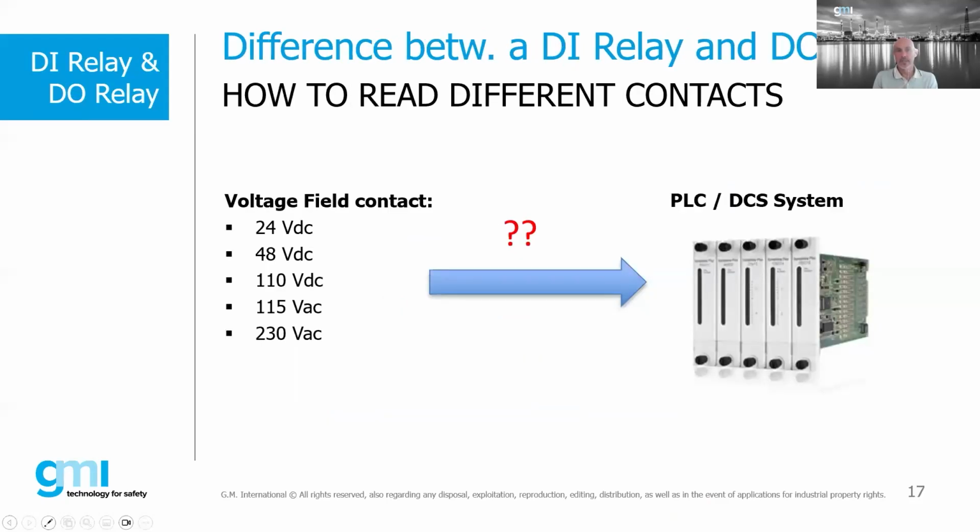Please go ahead, Gabriele, again. Sorry. So we were looking at a classic example where a proximity sensor, for example, has its status acquired by a galvanic isolator and sent to the system. In case we need a wet contact in the field, we then have 24, 48, 230 volts. Then we shall use a relay, which is a device that, depending on the voltage available at its coil, activates or deactivates an output and communicates such status to a PLC or a DCS.